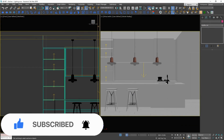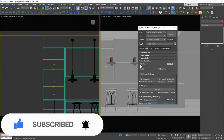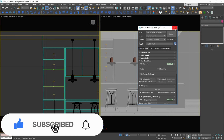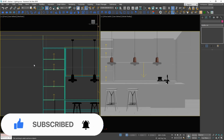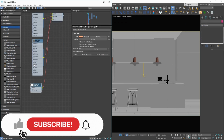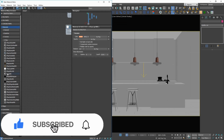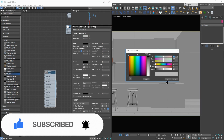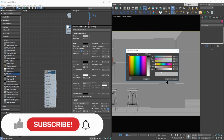In the third part, we will focus on materials. The first thing we need to do is to uncheck the material override so we can see materials we're going to apply. We will start with black wood. Let's create material, start interactive rendering and apply this to the model. Use almost black color.